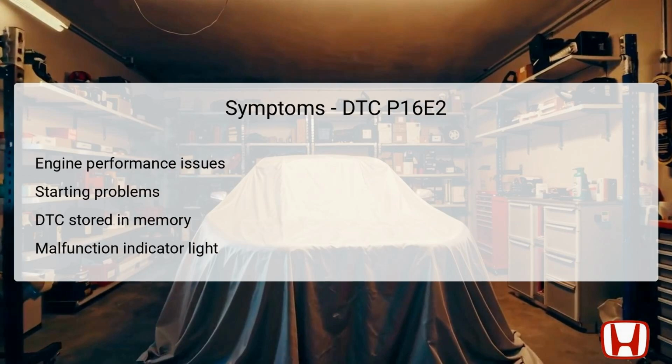The symptoms associated with DTC P16E2 can range from minor issues to severe operational problems. Drivers may notice engine performance issues such as misfires or poor acceleration, as the communication failure might affect system timings. Starting problems can also manifest, with the vehicle struggling to turn over.